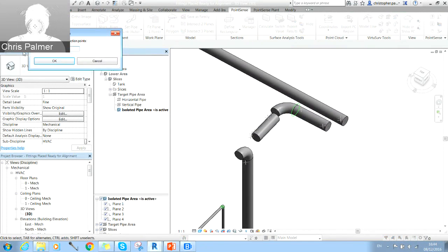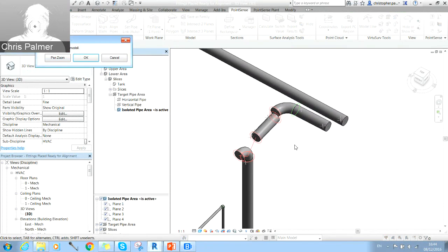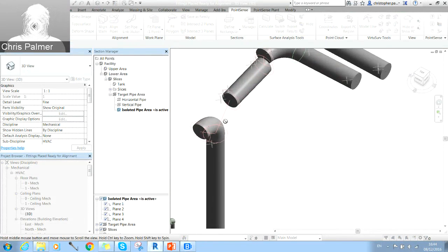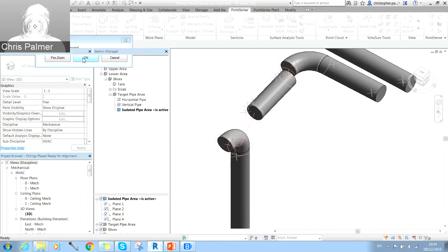So what I'm going to do is run the set pipe link auto tool, and I'm going to give it a nice big search radius of 600 millimeters. If we run this auto link, you'll notice it now finds those additional links between the pipes. It's actually found this one slightly incorrectly, so we'll see what comes from this. But if we go to, oh no, it's just graphical. So let's press OK to that.